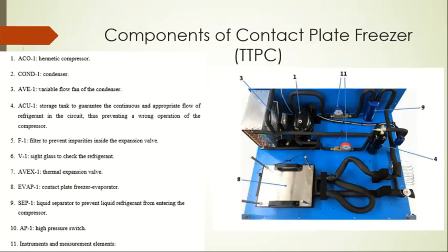The certain parts which were not included in the previous diagram we will include here, like 3, which is actually a variable flow fan. I mean, you can regulate its RPM, and in response to regulating the RPM, the air flows through this condenser and condenses the refrigerant. I mean, actually the air exchanges its energy with the refrigerant, cools down the refrigerant and condenses it as well.